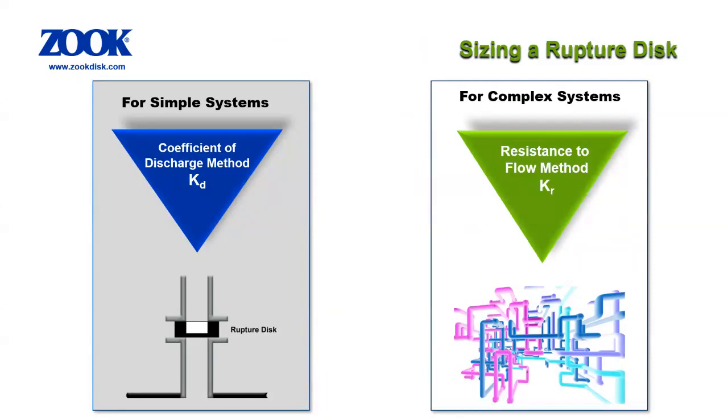Proper sizing of a rupture disk device is as critical as selecting the proper disk design. Undersizing will allow the pressure to rise to unsafe levels because pressure is being generated more quickly than it can be vented. Oversizing is equally dangerous because the device may not open as intended, resulting in a reduced relieving capacity. This is particularly true with reverse-acting disks that require minimum amounts of burst energy to open the disk as designed.